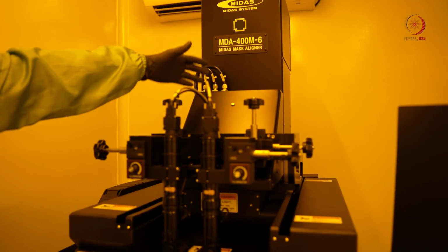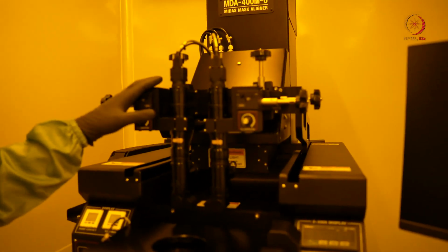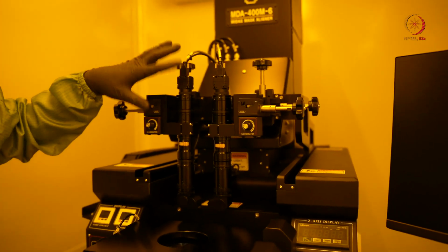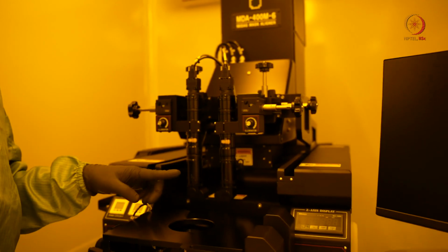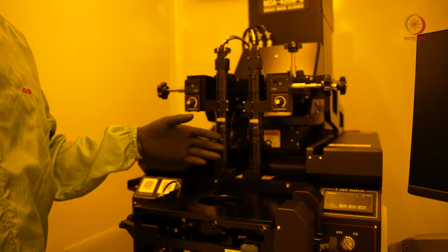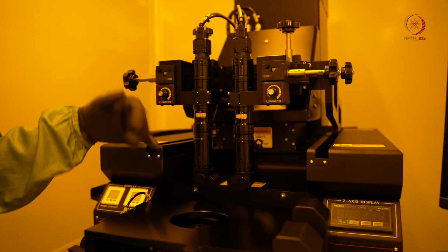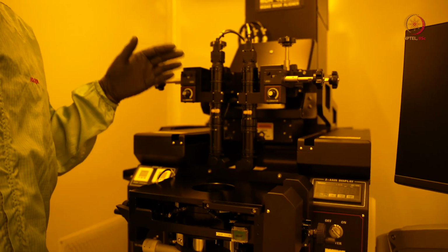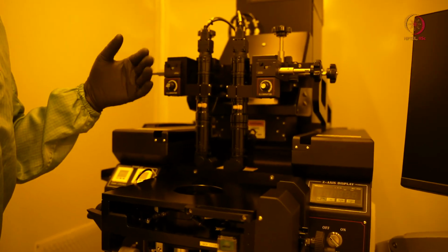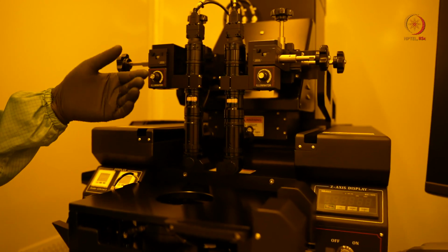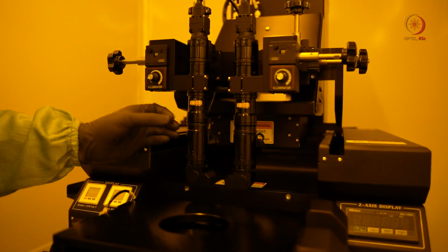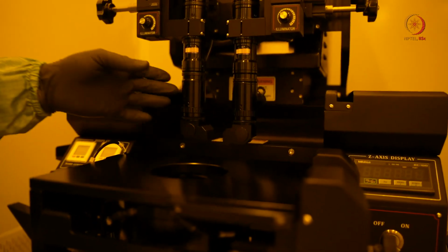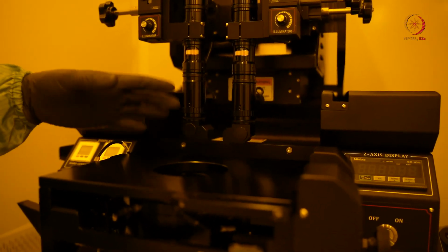Then we also have the microscopes which we use for alignment. The display from the camera output from the microscopes can be shown on the display in the system, so that we will be able to see the features very accurately. In the mask aligner, or in the microfabrication process, all the features are in the range of micrometers, right? So we need to make sure the alignment happens properly. That's why we have microscopes with variable zoom and focusing features to align the mask with the wafer properly.